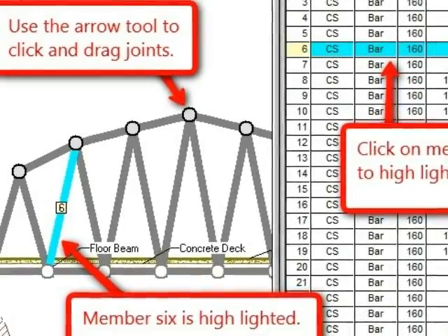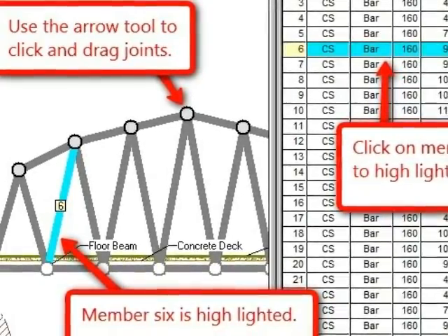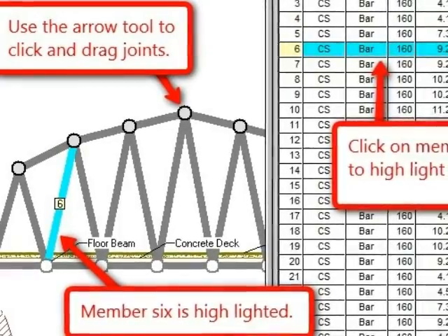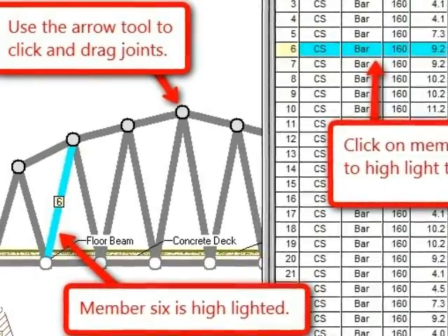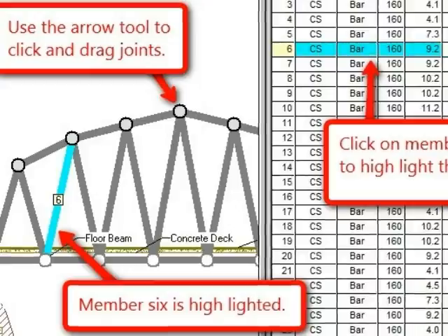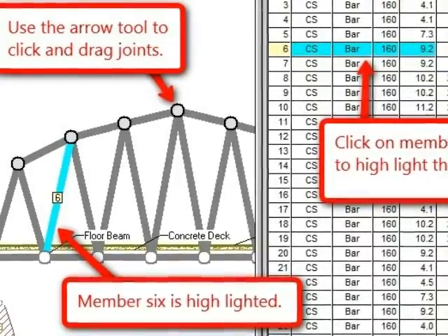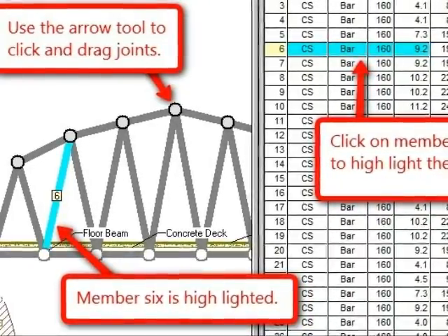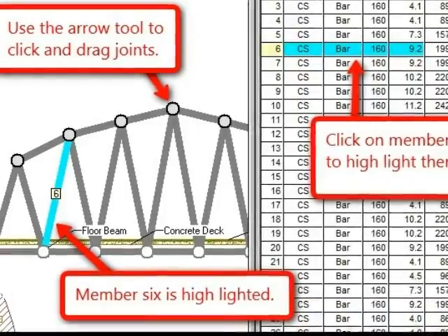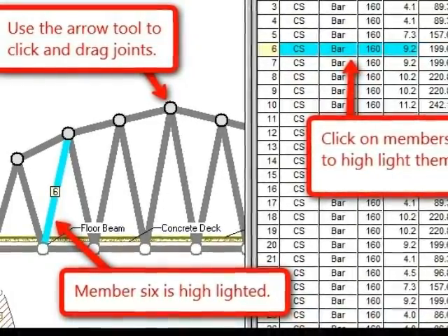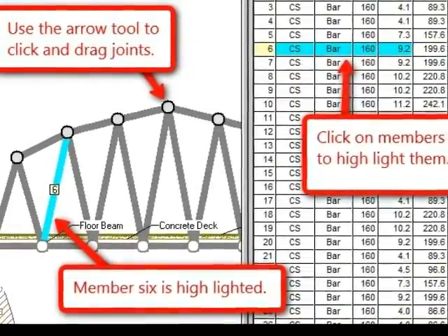Do you think steel is stronger in tension or compression? Look at your design in the chart and you should be able to figure that out. You should use this tool to determine which of your members need to be relatively stronger or can be less beefy. This will improve the efficiency of your design by both making it lighter and also making it less expensive.